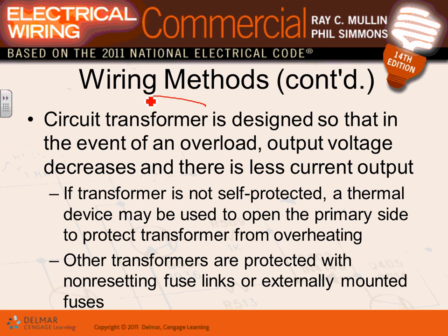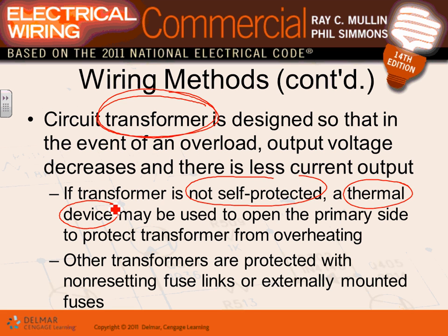All of them, guys, have to start with a transformer. These transformers are either self-protected, they call them self-protected transformers, or non-self-protected transformers. If they're self-protected transformers, Karen, if you overload the transformer, the voltage will dip down and deliver less energy. It wouldn't burn. If it's not self-protected, you are to install a thermal device to protect it, typically a fuse or some type of protection on the primary side, used to open the primary side and protect the transformer from overheating. So you put a tiny little fuse ahead of the transformer to protect it.